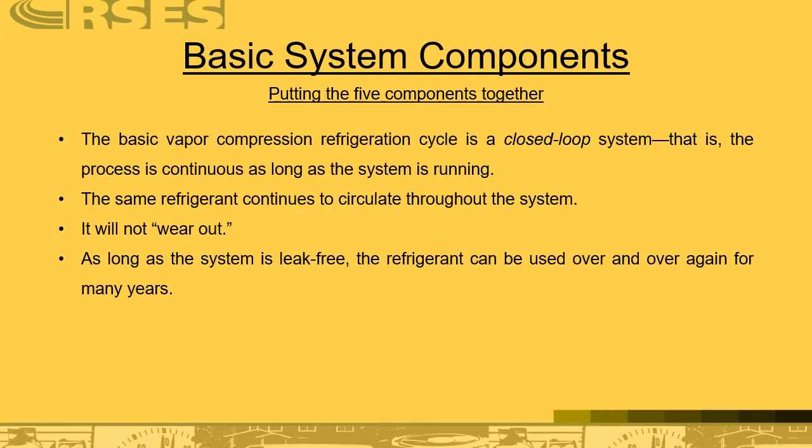I want to make it perfectly clear. There are people out there who tell you you have to change the refrigerant because it wears out. That is not true. Refrigerant never wears out. As long as the system is leak-free, the refrigerant can be used over and over again for many years. I have seen refrigeration systems work in excess of 40 years without any problems.